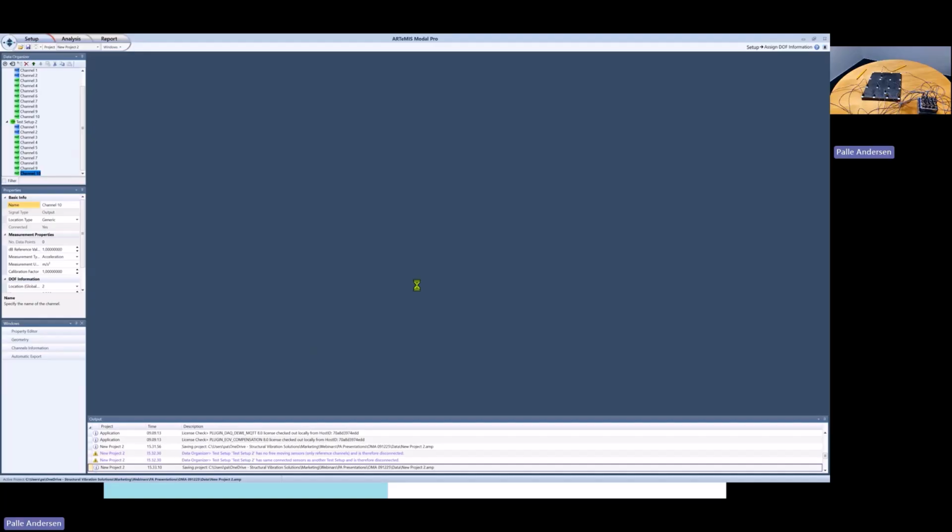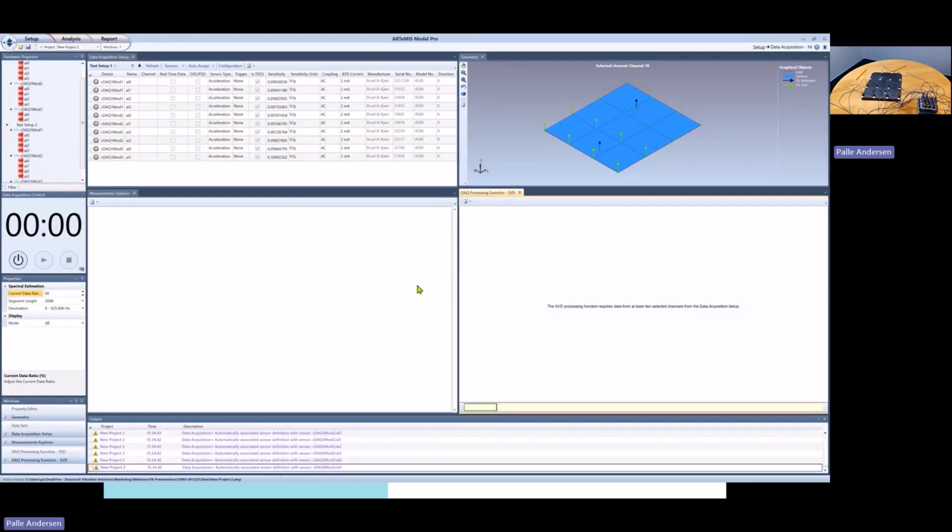And we simply connect here to the data acquisition task, which we see here. We have the 10 accelerometers connected here. This is what they are called if you look at it from a National Instruments point of view. What we would like to do is tell how the sensors we have defined in our project are linked to the hardware channels that we actually have available.